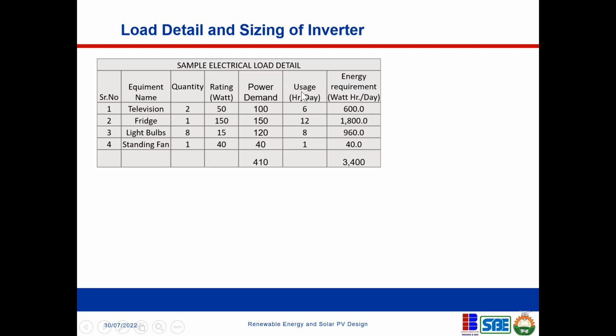And again, it is also important you understand the hours of usage for those loads. Now, the hours of usage will enable you to size the battery bank. It could be possible that you size for a load that could run for 6 hours, and you could size it, for example, for 3 kilowatt hour.